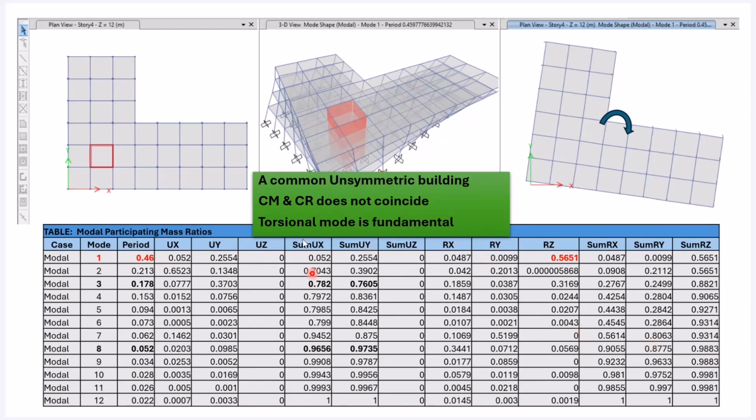But this is not a usual behavior that you should design a building for. So what we did, I did only a couple of iterations quickly, and we have moved the same amount of shear walls, which was used as a core wall here. It doesn't mean that you should not use a core wall, but the distribution matters.